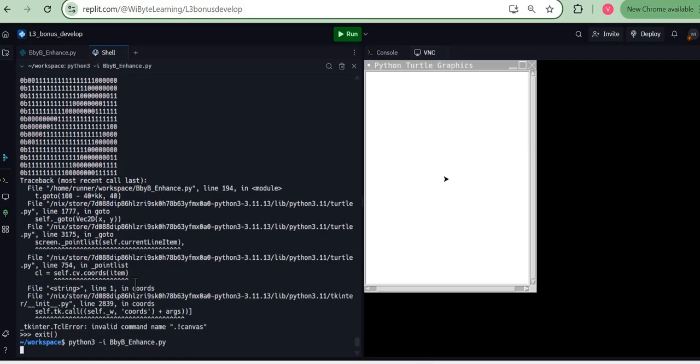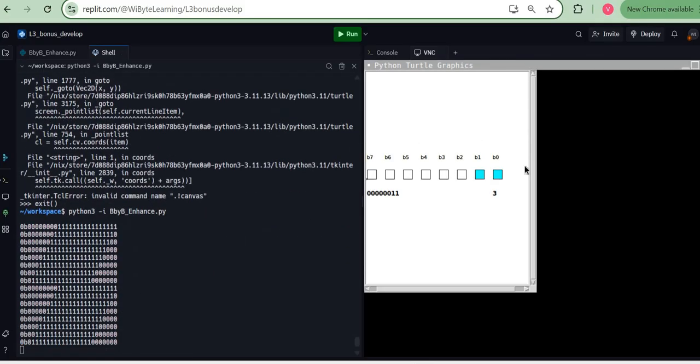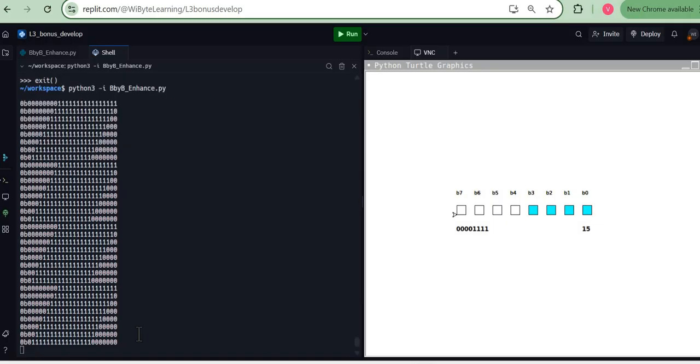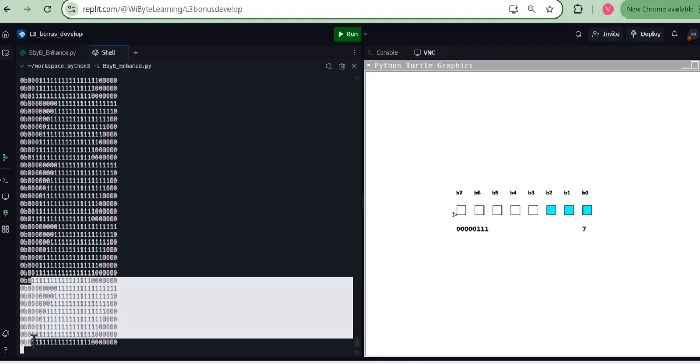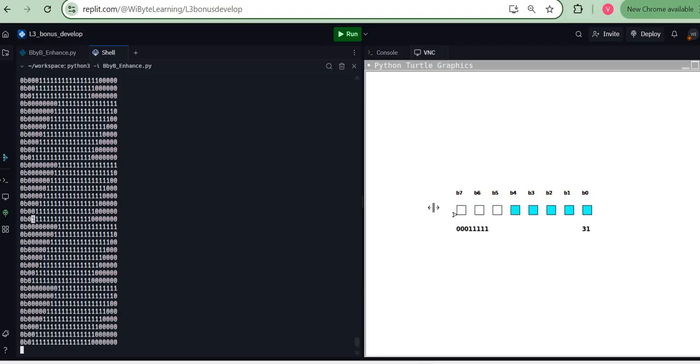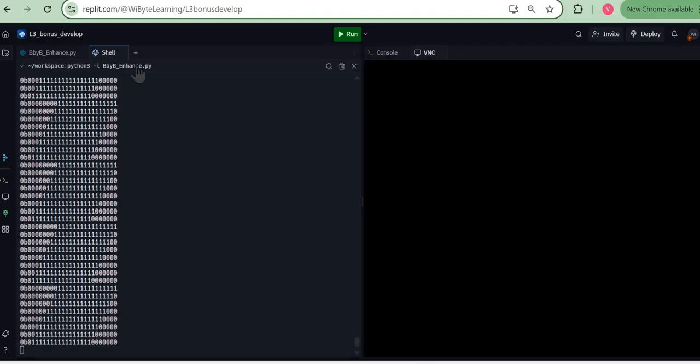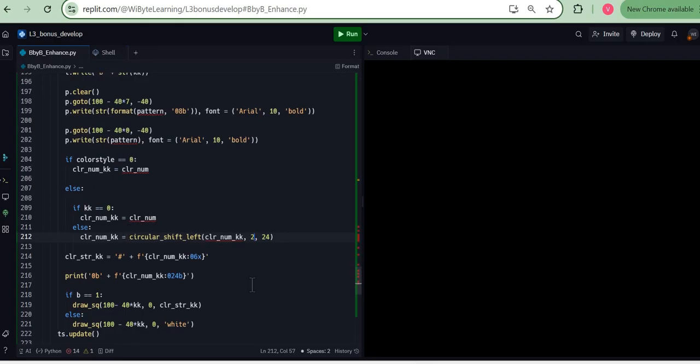So when I run this, you notice it looks all cyan, but there's a tinge of green coming in, because it's becoming more and more green, and that's very visible here on the last LED. It looks pretty much green because blue is almost out, right? There's a little bit of a tinge of red here, but red is not getting maximized because the last bit is still not being touched, right? Let's say I make this shift by 2.